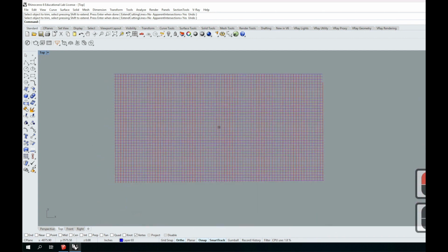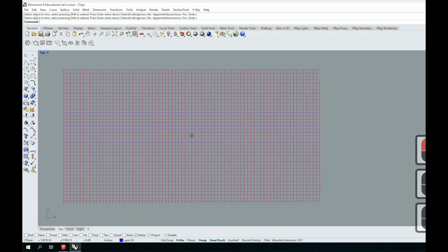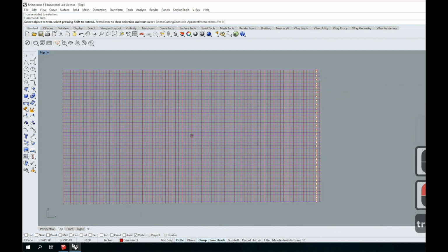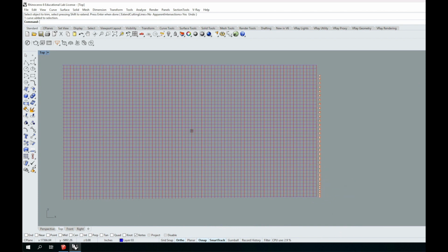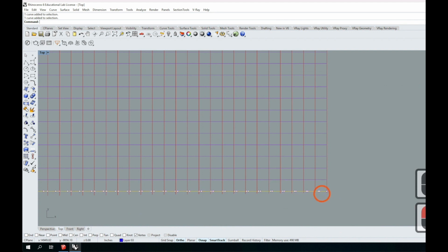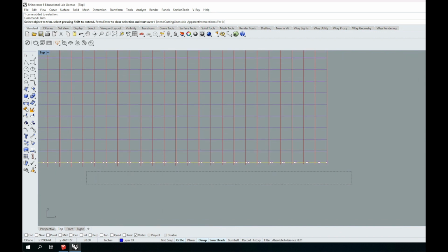And then it's time to go ahead and do the same trim on these other sides. So let me use this line here. We'll type trim. And we'll trim off all of those line segments. Here I end up having to select and delete that piece. Let me go ahead and trim all of these off. It's possible for me to get in and trim those, though it's a little bit more work. I could do trim and come in here and kind of do this in two operations. But I have to do it zoomed in.